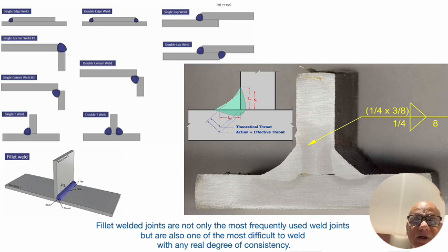So groove and fillet joints are also used quite often where a stress riser or a notch is not acceptable. Critical equipment, like in nuclear and other industries, will many times have this vertical member with a slight groove or a Z on both sides or a single side, which is welded first, and then on top of it we build the fillet.